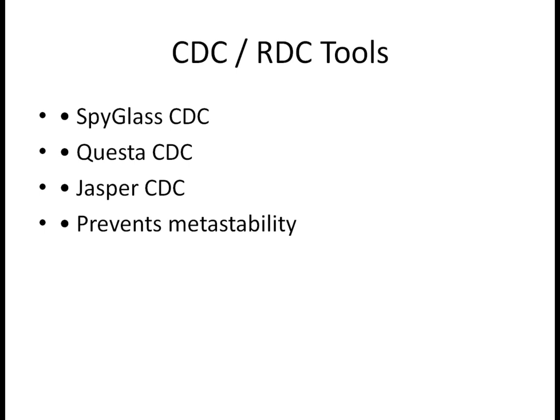And here one more concept I would like to add on metastability, called MTBF, which is mean time between failures. There is a formula where we use the synchronous data frequency, the signal frequency, and the setup and hold window. Through that, we get the MTBF value. From this MTBF value, we can tell how long the data will be stable and after what time the flip-flop will fail. So from the metastability value only, we can tell when your flip-flop will fail.